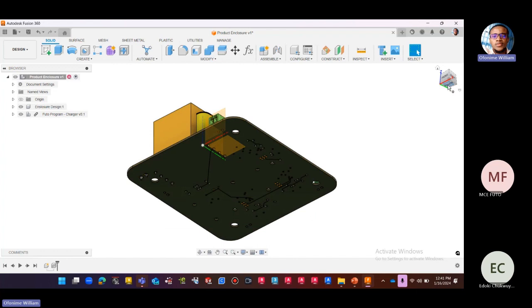And the beauty of it is that you can orient the plane, position it in almost any way you want, 360, inclined, and so on. And however the plane is pointing or is oriented, that is exactly how your sketch will behave. So your plane, more like the board you're using to draw, will influence how what you're drawing will come out. So I just wanted to put that out.